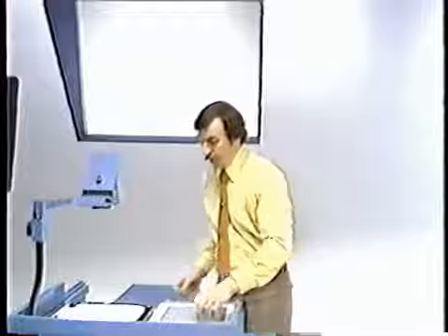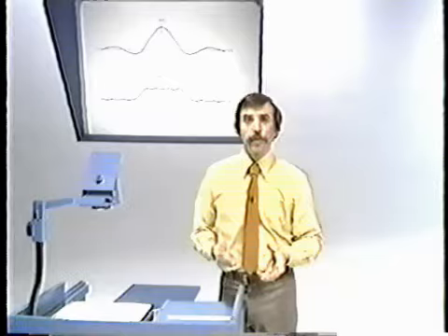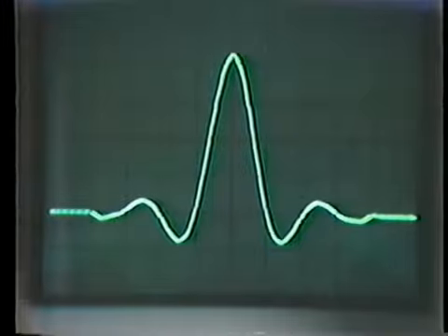And so what we'll see after the low-pass filter for the impulse response is a smooth curve like this, but also as part of the demonstration, what I'll do just to show the zero-order hold is to take the low-pass filter out temporarily and then put it back in. So first, let's just look at the filter impulse response. What we see here is the impulse response of the overall system. And we observe, for one thing, that it's a symmetrical impulse response. In other words, it corresponds to a linear phase filter.